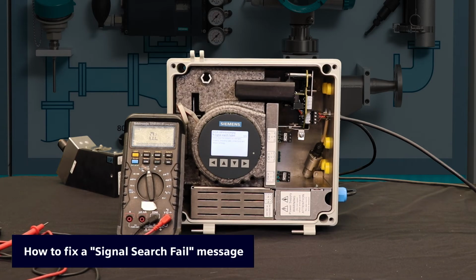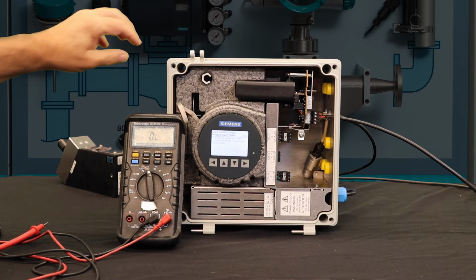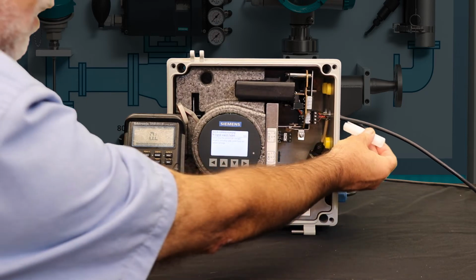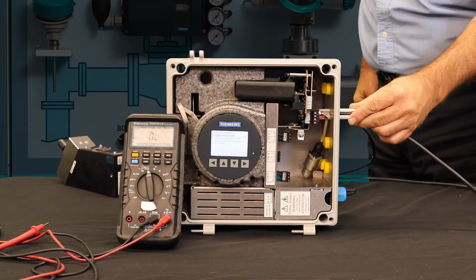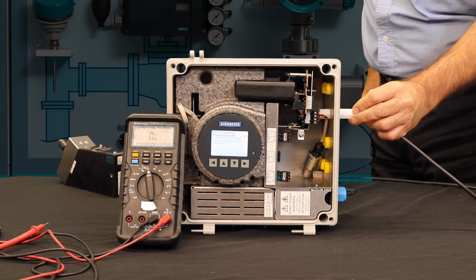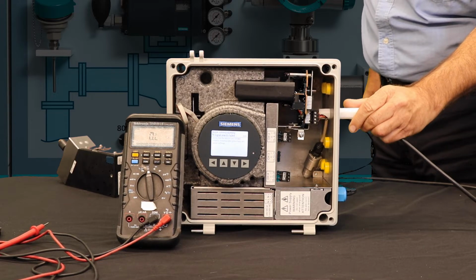One of the more common reasons you'll have a signal search failure is due to a poor cable termination. On the transmitter end, you'll want to use the extraction tool for the cable. Slide it in. You might want to make sure that this has been tightened in all the way. And if you've found that both the up and down cables are completely tightened and you want to check the continuity, you can remove these cables,